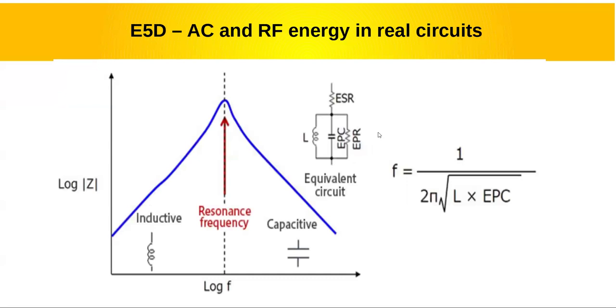You mentioned, if I can ask a question real fast, that that last formula on the last page was because it was in parallel. Did I hear that right? Yes. So the model right in the middle picture, the equivalent circuit you're dealing with now for an inductor, you've got the equivalent parallel capacitance and parallel resistance. All those are in parallel when we're talking about inductors. But when you had the slide up a minute ago for capacitors, then the effective elements that we have there are actually acting like they're in series for capacitors? Correct. Because it's a series LC circuit for a capacitor. You've got the inductance of the leads that are in series with the capacitor. And then you may have some parallel resistance, effective series resistance in parallel with the capacitor.